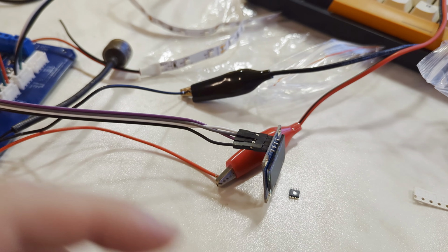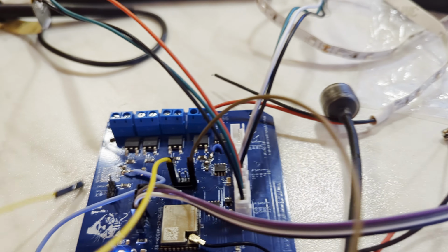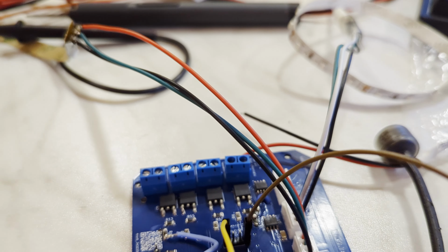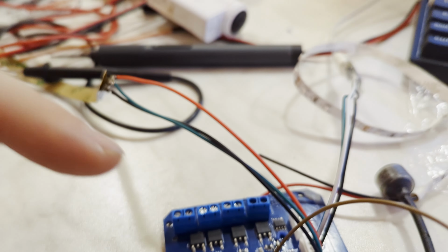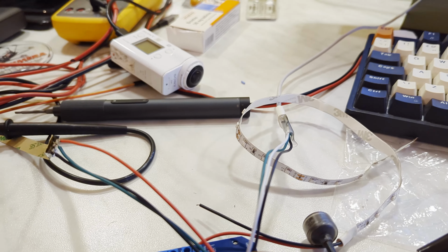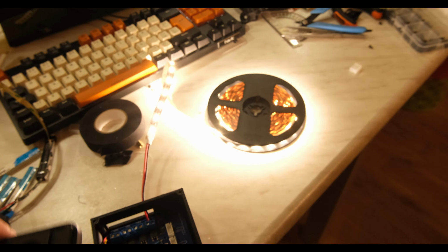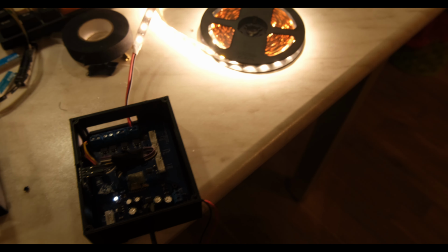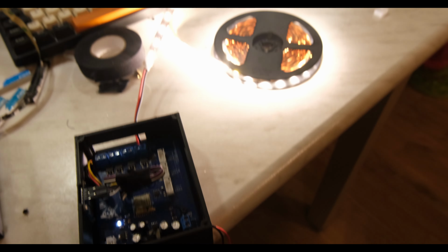The reason why it wasn't working is that I had an error on the schematic. It should be pin 3 going to SDA and pin 4 going to SCL. God. No error counter +1. Don't look at my table, it's really messy now. But, damn it, it's working!